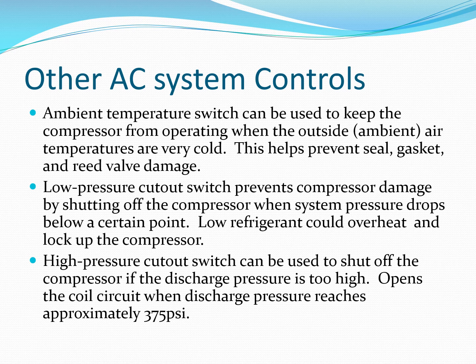This stuff is readily available for the do-it-yourselfer, the everyday person, to just buy a can and charge their own system. As technicians, we don't like that, because what happens in a lot of cases is that they have another problem that's causing it to blow hot. It's not the refrigerant system. And so they keep putting refrigerant into the system, expecting it to get colder, and it doesn't do so. Before you know it, you have a system that has two problems. It's got the original problem that, I don't know, might be a blend door in the dashboard that's not directing the air over the evaporator. Instead, it's directing over the heater core.